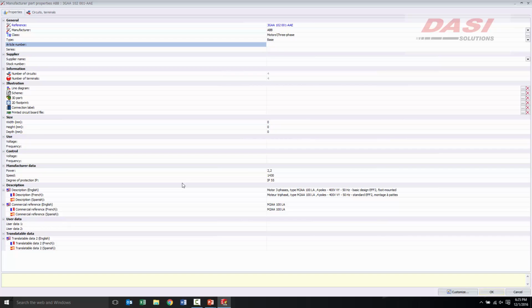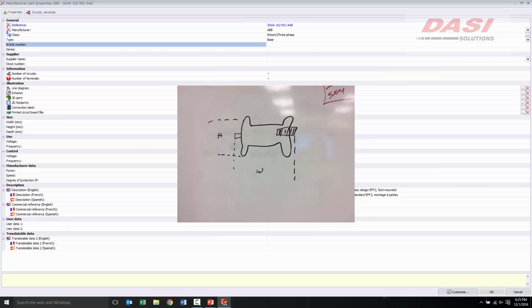The size. This will designate on the footprint how much size it takes in real estate when you are placing it on a physical floor. When you go to draw it, what it's going to do is then scale that for you. Whatever your drawing scale is, it will then readjust these sizes to be realistic to scale, depending on what the scale is of the drawing. So if you say 1 to 10, then the motor is going to be so big.